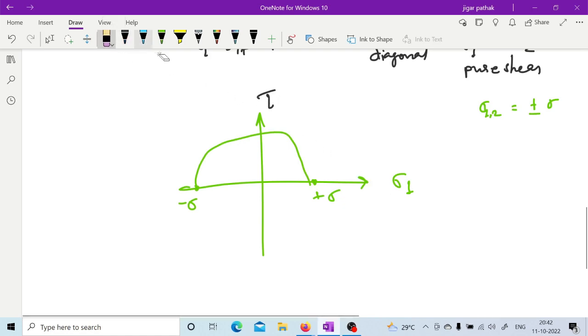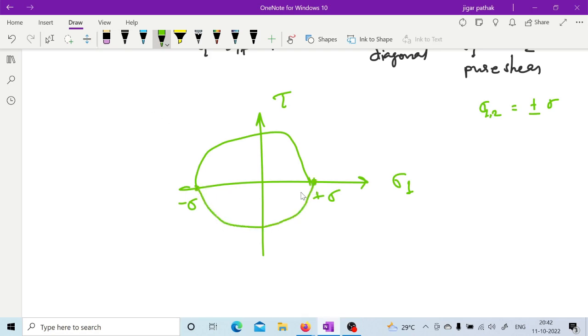So here, this will be your Mohr circle, right? This is the condition of pure shear, where this is the normal stress sigma and this is tau in your Mohr circle. The normal stresses are the same in magnitude and only different in nature, tensile and compressive, which will give you this pure shear. And in pure shear, this will be your condition,